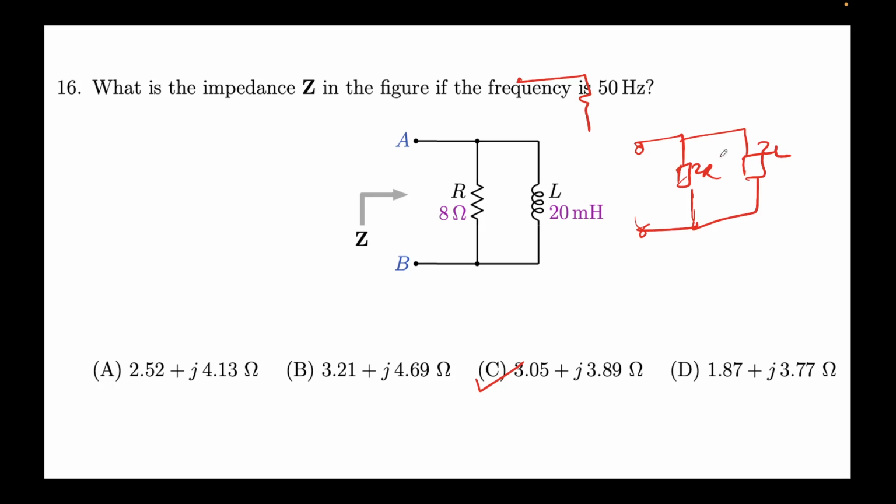Right now, for instance, it's a very simple problem, ZR and ZL, but even if there is a complex circuit involved with multiple voltage and current sources, you can apply superposition and Thevenin Norton equivalent. Everything else will remain as it is. The application will remain as it is, just the format will change, and that's all you have to worry about.